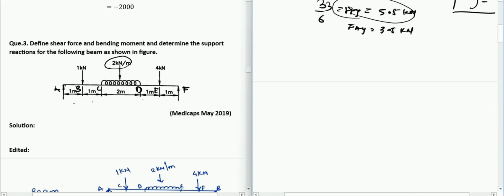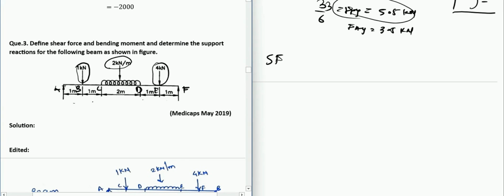So let us try to find shear forces now, which is our step 2. Whenever you have a sudden point force, like here and here, you can calculate shear force before A and after A. It will give you a clear visualization of how the shear force is changing there. It might get confusing sometimes if you are trying to calculate at that point. So let us say at B, at C, at the UDL or the DE. Whenever there is a sudden point load, you can try to calculate before and after that point.